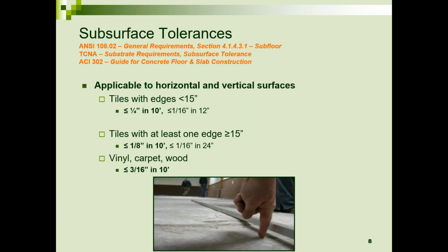As far as floor flattening, the requirement for large tiles, greater than 15 inch, you'll see there in the middle of the slide, is no greater deviation than 1/8 inch in 10 feet. If you have a floor flatness problem greater than 1/8 inch, you're going to have to remediate or fix that, meaning getting it below 1/8 inch in 10.